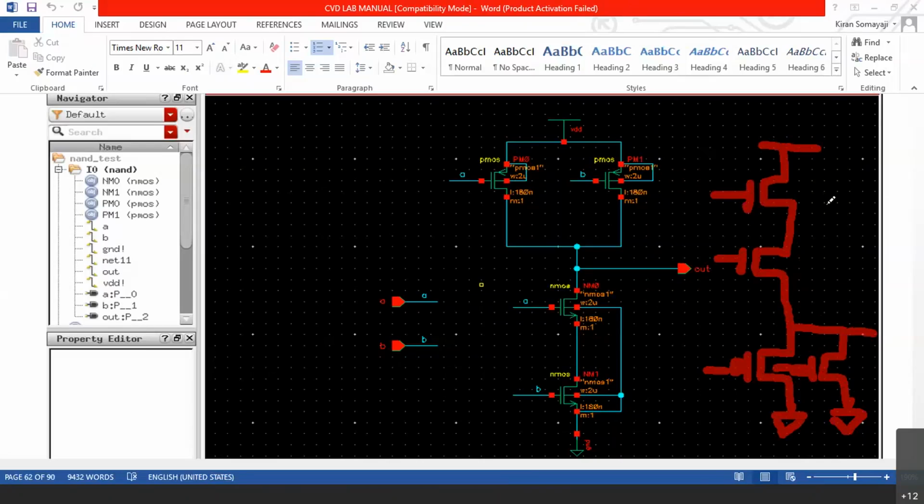Yeah, tell me. For the second circuit, we'll get output as 0, 0, 0, 1, sir. Correct. So is this an AND gate is my question. Yeah, sir. But they don't use AND gate at all. They always use one inverter along with the NAND gate. In CMOS, there is nothing called AND or OR. There is only something called NAND, NOR, and inversion.